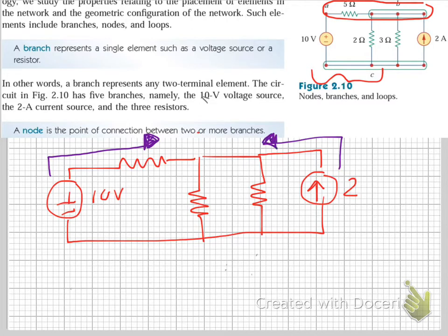This is another current going into here, right? So this means the sum of current 1 and current 2 is going to split between here and here, right? The way it's going to split is dependent on the current division law, right? So let's say I'm gonna call current 1 and current 2, the sum of it equal to IT.